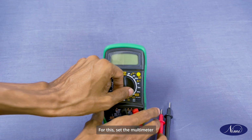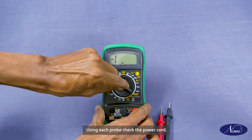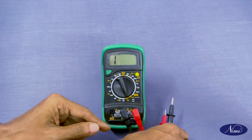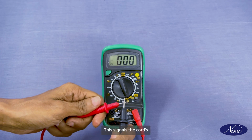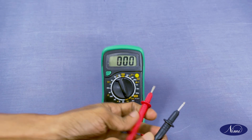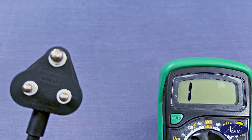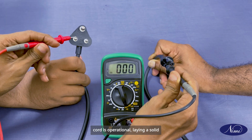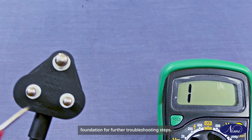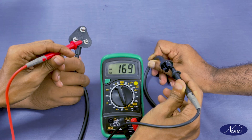For this, set the multimeter to continuity mode. Using each probe, check the power cord. Listen for a beep or check for low resistance. This signals the cord's proper functionality. Our initial test confirms that the power cord is operational, laying a solid foundation for further troubleshooting steps.